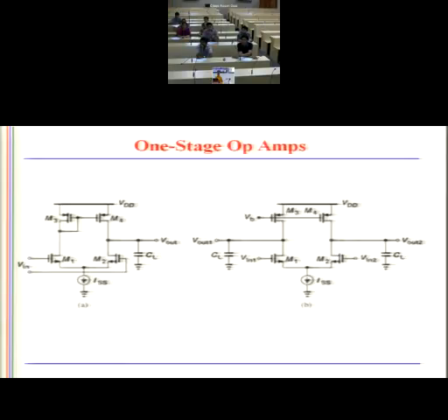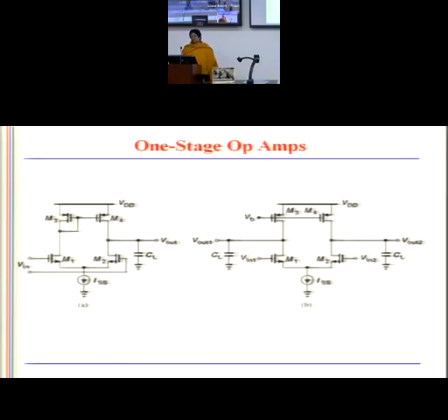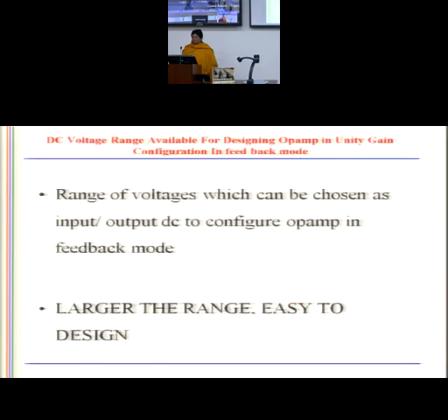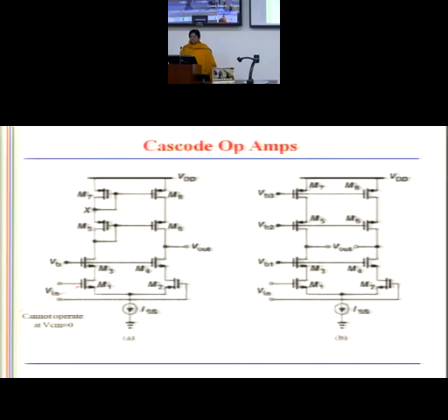No, ma'am. So we move on to the next, that is for a high gain. Now I want to increase again. Look here. If I want to increase again, look here. What am I doing? Cascoding. Cascoding in the input. This is a driver section to which I am feeding the input. This is the load. So I am doing cascoding in both, in the load section, that is the upper section, and the driver section, which is the lower section.